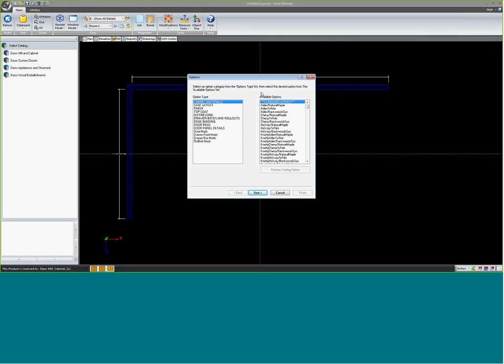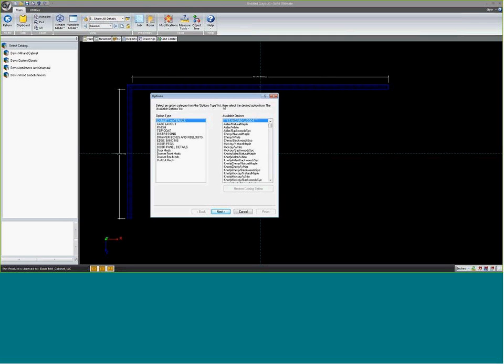So just quickly, most of you have seen this already, but I want to talk about a couple of points on this, because you want to make sure every time you start a new room to pick the specifications you want for that room. A couple of things are important to know, though, under cabinet materials. If you have 2 things listed there divided by a slash mark, the first one is your exterior wood, the second one is your interior. So in this case, it would be cherry veneer exterior with natural maple melamine interior.